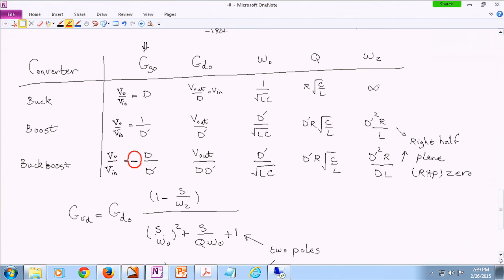All right. However, the homework assignment that I assigned to you is the opposite of this. So your last row should be very close to this, with the minor difference that you're assuming your output voltage is positive. In other words, your voltage gain is D over 1 minus D. It is not negative D over 1 minus D, okay? This is because the polarity for the capacitor that you have assumed is this way, right? Something like this.